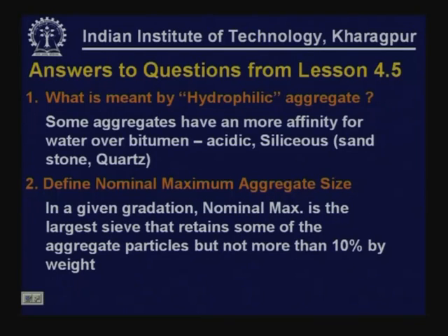These are called hydrophilic or water loving aggregates. Usually these are acidic in nature. These are normally siliceous aggregates, typical examples being sandstone and quartz.